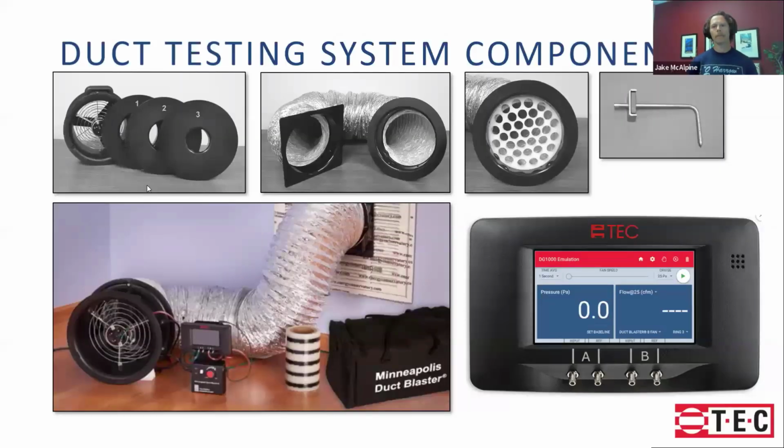Yeah. So when you do a duct test, whether it's a total duct leakage or leakage to the outside, you've got some system components. So, in this image here, we're seeing you've got a fan, you've got rings on those fans. So I kind of think of those as like gears in a car. They're calibrated to work at certain leakages. So for very leaky things, you'll use the bigger hole or no ring at all. For tighter houses, you're going to use an increasingly smaller diameter hole in the ring.